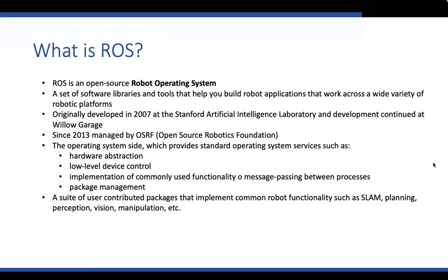For example, you have a process used for the motion of the robot, and another process used for camera configuration and detection. You need to tell the robot to move when the camera detects something, so these processes need to talk to each other. ROS is very helpful here, and we will see how it sends information between the two.